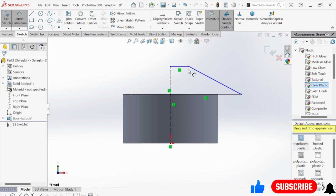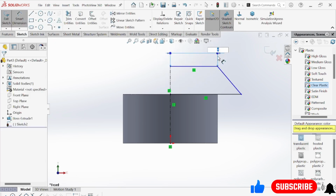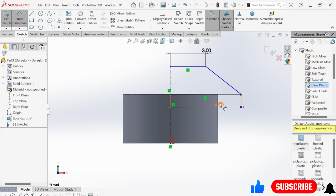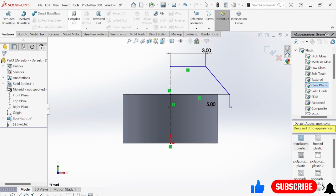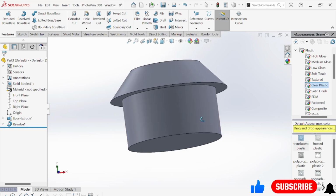Now come here, give dimension 4 mm. Actually not 4, let's make this one 3. Okay, and let's make this one 6. It's not 6, let's make this one 5. Yeah, 5 looks fine. Go to feature, go to extruded, not extruded cut, select revolve boss base, and make this one okay. Now here you see it happened because line 1 is already selected. This is the upper part.